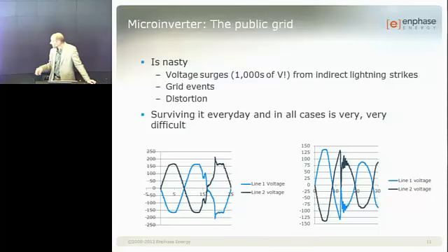You can see on the right-hand side, here's what happened: this was a working location. That's also some waveform we picked up from the field. Everything was fine, and all of a sudden, you see not only a very fast reduction of voltage, but also a huge phase jump from the first half cycle to the next half cycle. That happened because it was at the end of a three-phase transmission line, and one phase was lost. When that happens, it changes the instantaneous phase shift on the voltage. So you have to take that too.